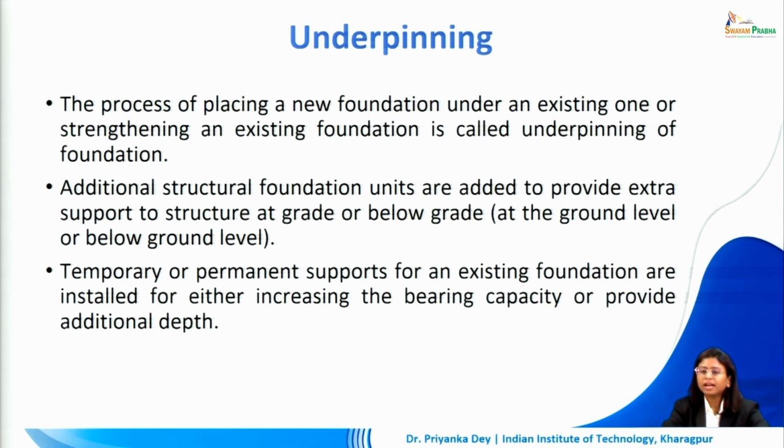Or let's say we have increased the load on the building or have created additional floors on top of our existing building and the old foundation is no longer capable of taking this new load that we have placed. In this case, we can go for underpinning and it will allow us to actually alter the existing foundation, make it better without destroying the superstructure that is being supported by the existing foundation.